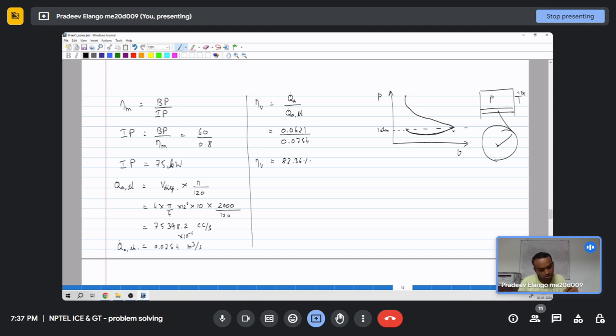and after ignition and compression the pressure will rise. Around TDC the pressure will be at its peak, and then during expansion the pressure will drop as the volume keeps increasing. After the BDC there will be an exhaust stroke where the gas is pushed out, so there will be a pressure a little higher than atmospheric pressure. Now we see that the pressure inside the cylinder is not constant, it is always varying during suction, compression, expansion, every time it is varying.